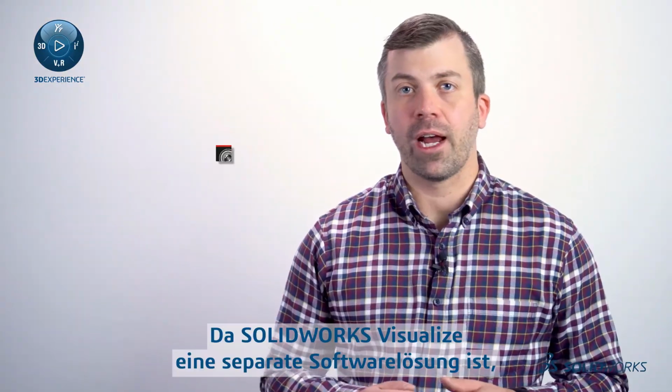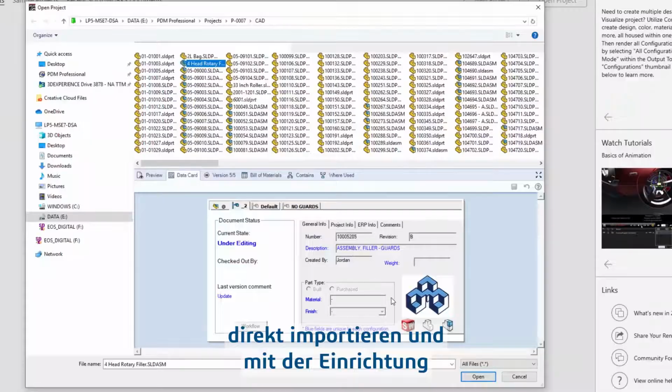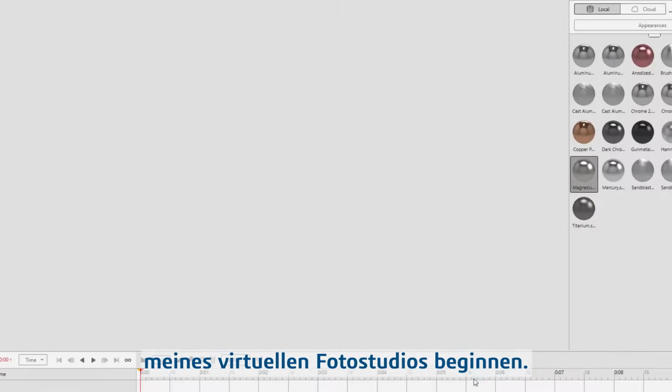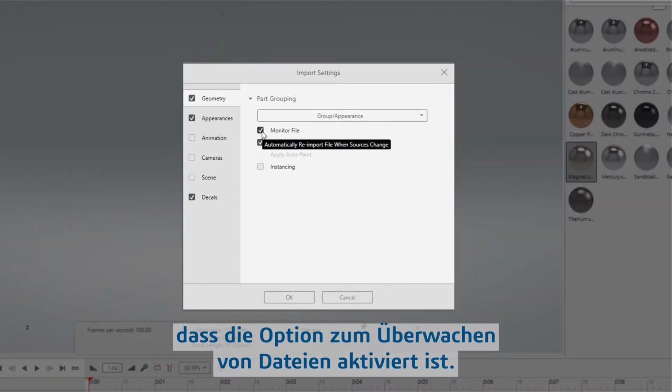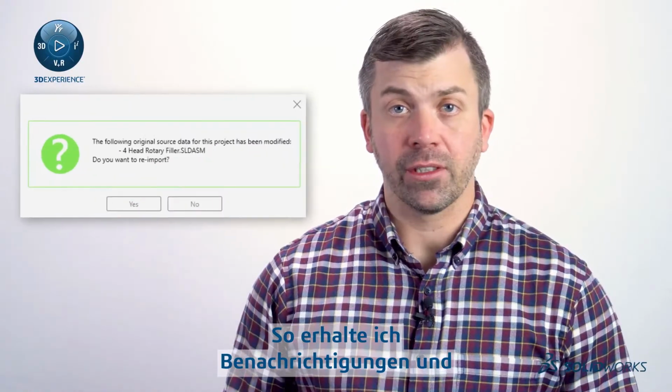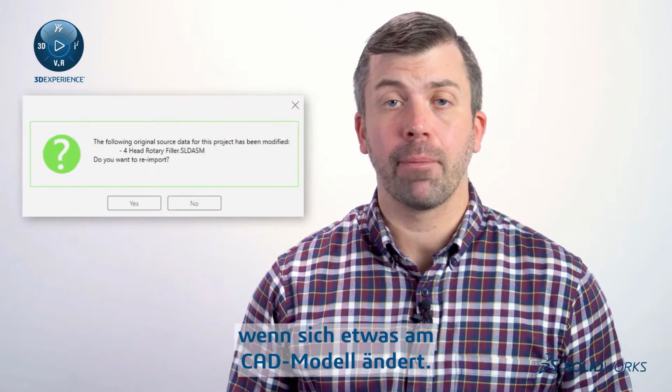Since SOLIDWORKS Visualize is a separate software, I don't have to worry about tying up a CAD license from our engineering team. Visualize lets me directly import the CAD assembly to start setting up my virtual photo studio. I always make sure to enable the monitor file option. This will give me notifications and allow for live geometry update if anything changes to the CAD model.